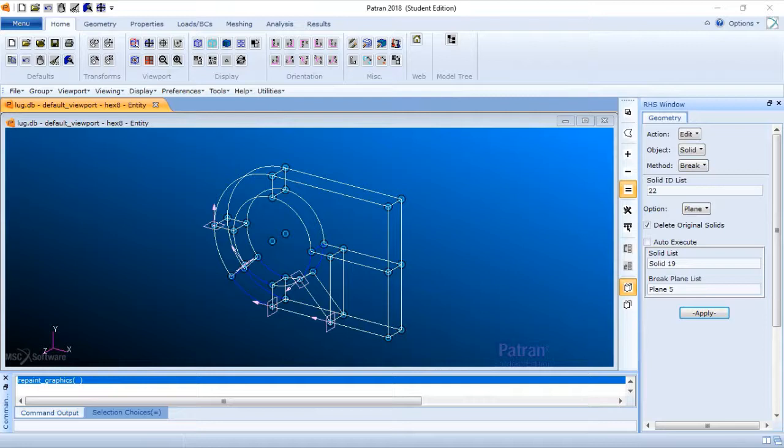Well, those were the last ones, but for now we're gonna delete the 2 top solids since they are not used for the isomesh meshing. So we're also gonna delete all the planes because they are no longer needed. We needed them just for breaking the solid, and now that we have done it, we're gonna erase them.